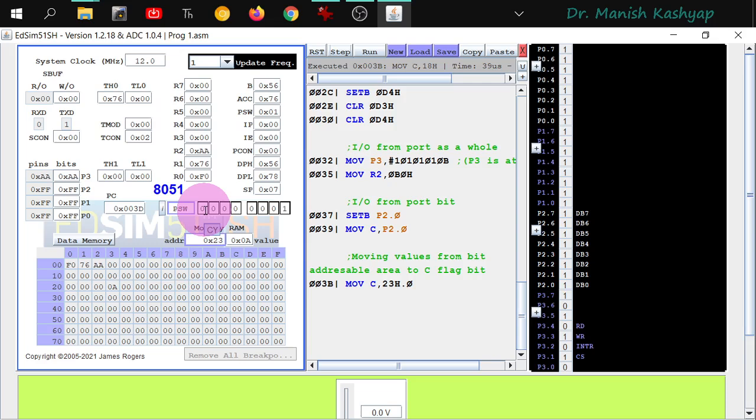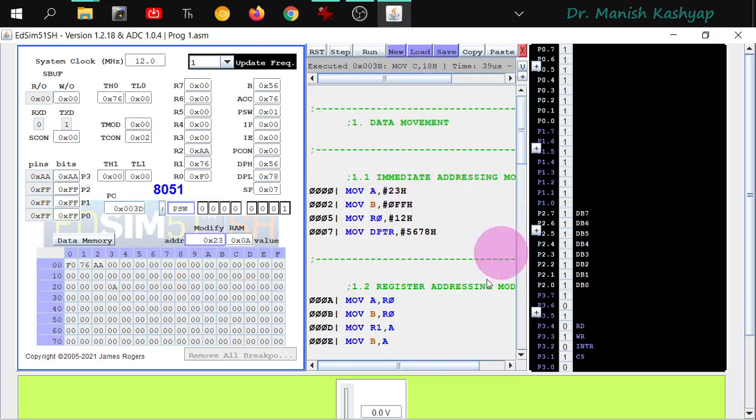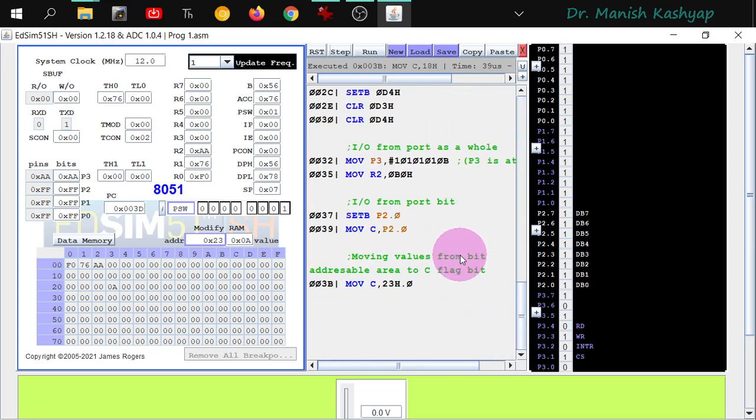So this is how simple operations within the internal registers and this RAM of 8051 can be made by us. And an important point to note here is that in today's lecture we have only addressed the internal addressing modes. For being able to access the externally interfaced RAM and ROM, we do not have this MOV instruction. We have MOVX and MOVC instructions, right? So we will talk about MOVX and MOVC instructions, not this MOV C. That MOVC is MOV with no space, C. That means it's a complete one thing, MOVC. So we are going to study that when we will study more programs.